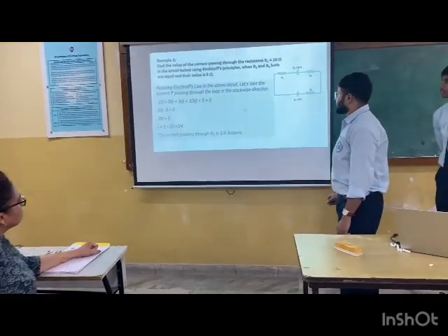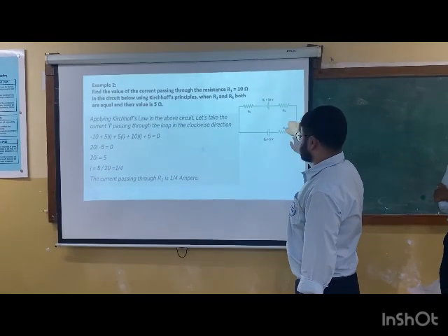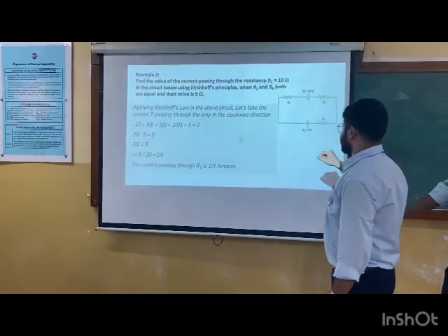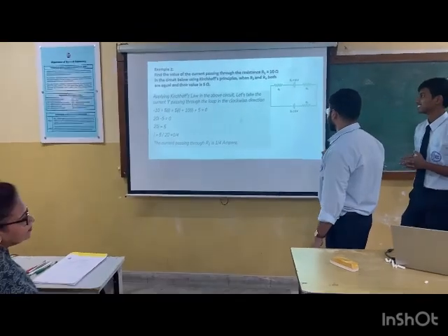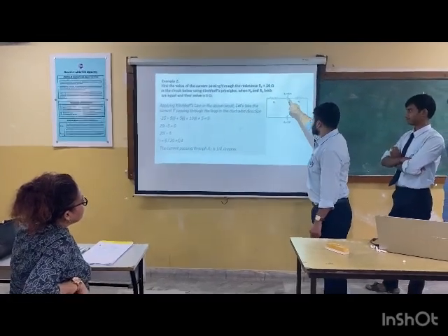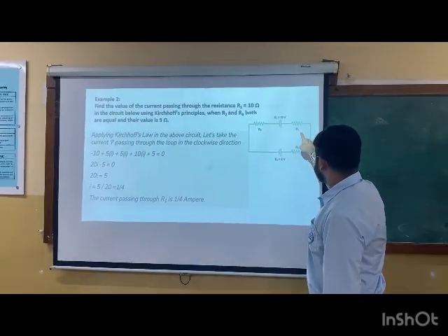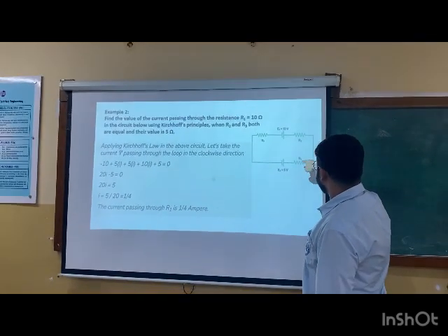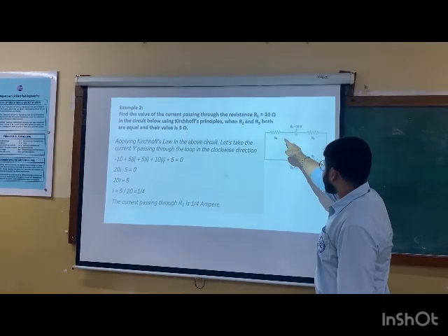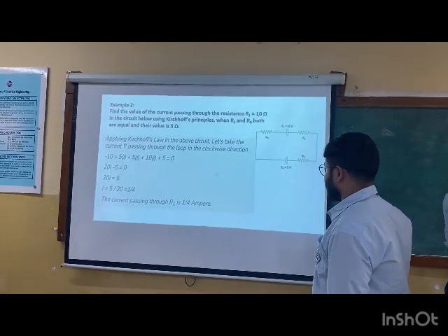This is the KVL example. In the circuit diagram, going anti-clockwise, you show the current I there. Starting from here, we take -10, then 5, there is 10 volt across R1, then 5 volt, and then we get the current as 1/4 ampere.